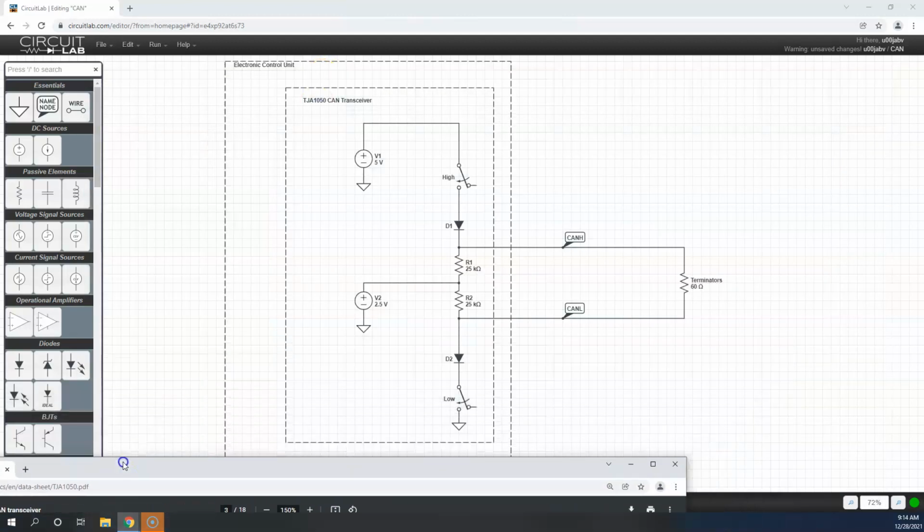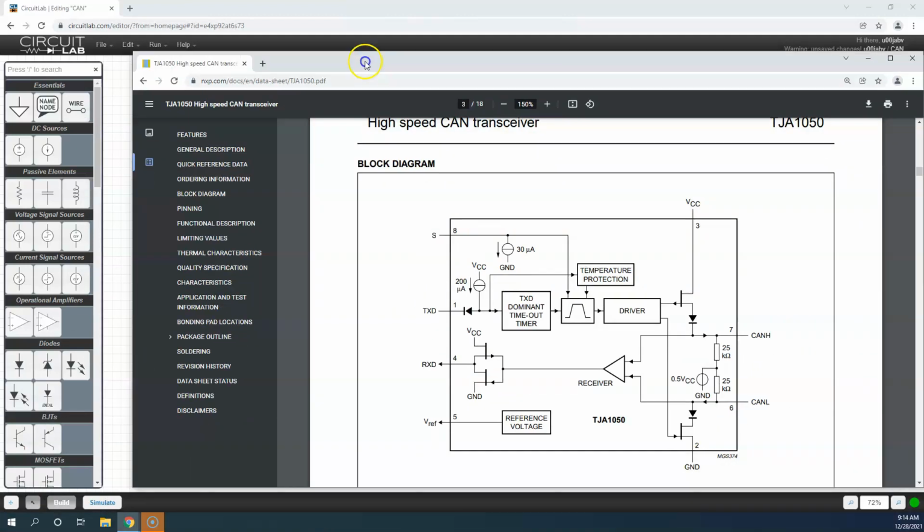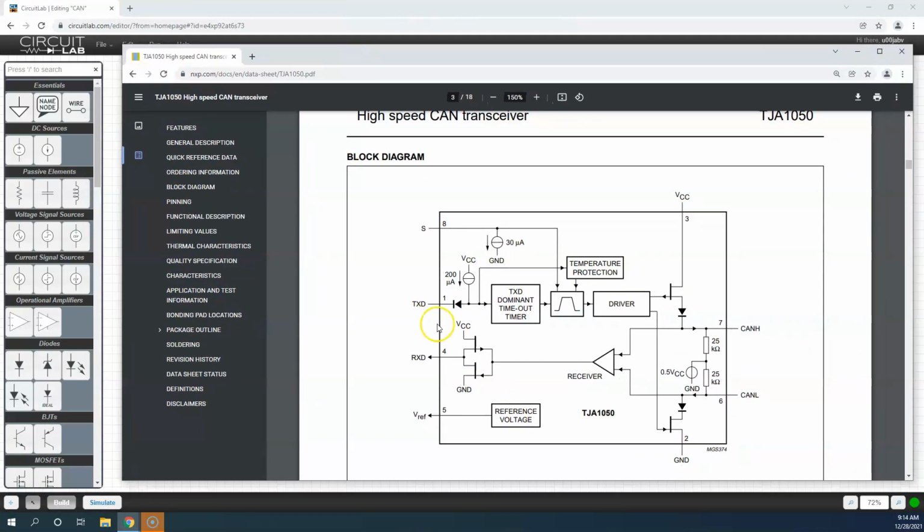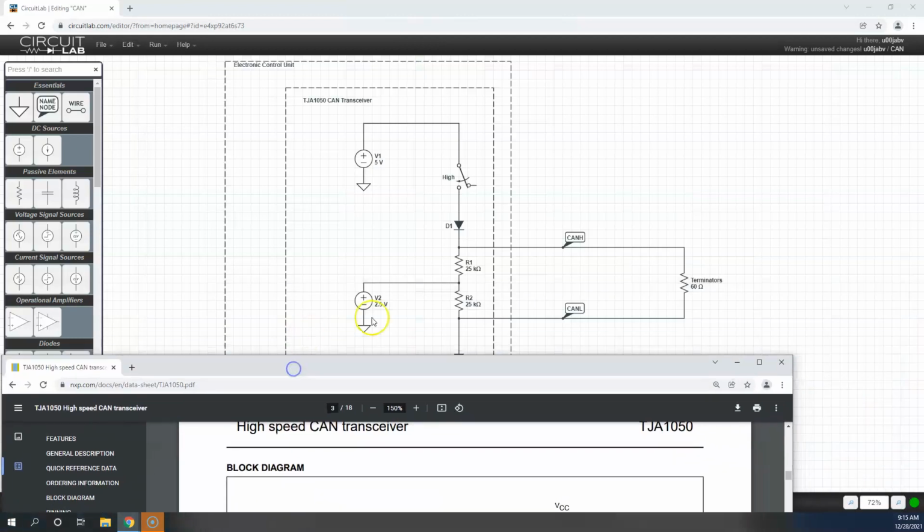I've replaced those with switches because everybody understands how a switch works compared to a MOSFET. So you can imagine this is like a finger that's flipping the switches, and it switches both of these at the same time. So it's either provided with the 5 volts and ground, or it's not. Also contained within this is something that indicates 0.5 VCC, so that means 0.5 times VCC, or 2.5 volts. So half of VCC is what we care about here, and we're going to hold this at 2.5.